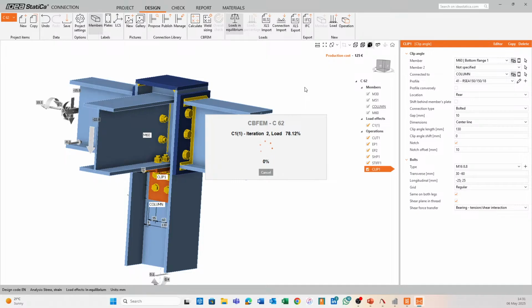I think this might actually bring us to a place where we might need to upsize our members potentially, but hopefully we can get away with not having to do that. I do doubt it, I must admit. I'm not optimistic looking at where our plastic strain is sitting at the moment, but we can bring it down significantly by using the different operations we have available to ourselves.